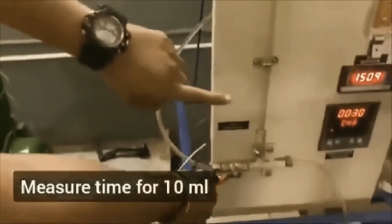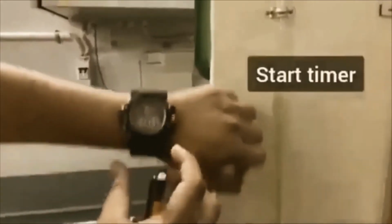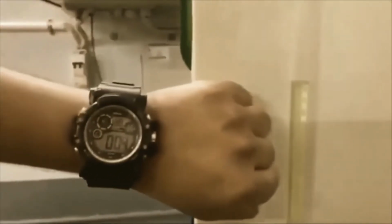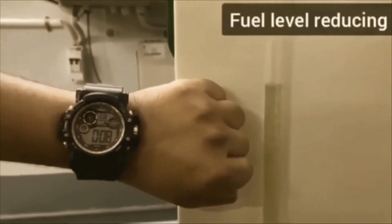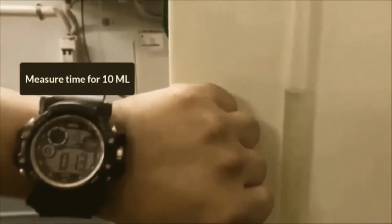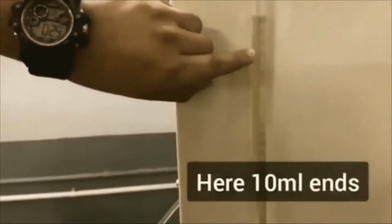Here we measure the water column for the airbox method, and for the fuel consumption we measure the time for consuming 10 ml of fuel. Here we start the time. Here the fuel level is reducing. We have achieved the 10 ml fuel consumption, so we stop our watch and take the reading. Here you can see that the diesel level is reducing.